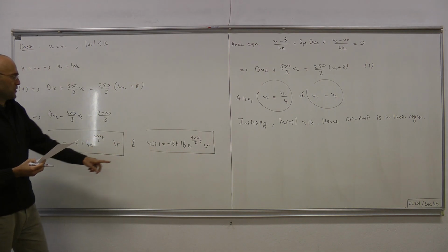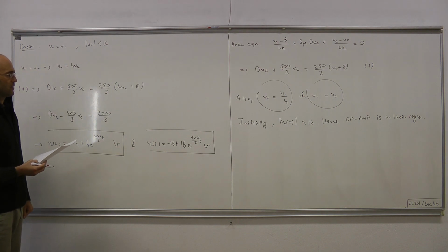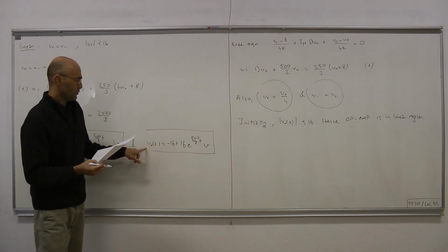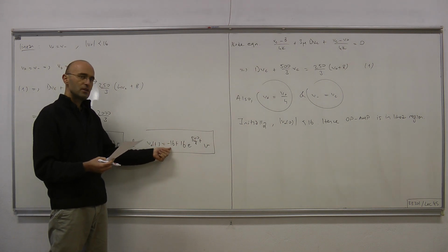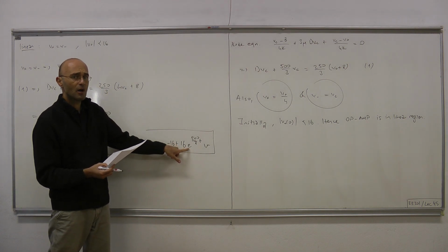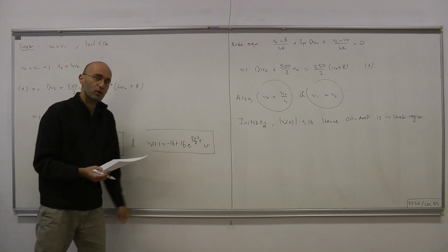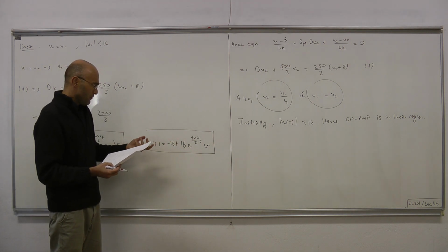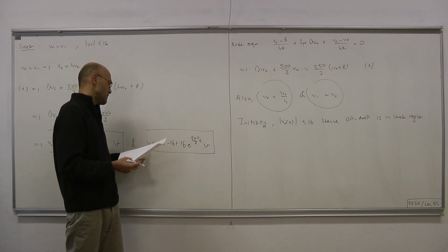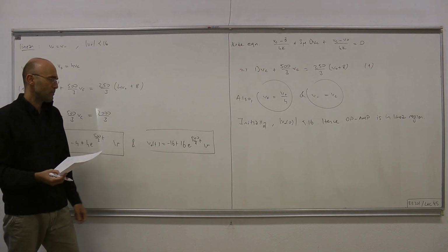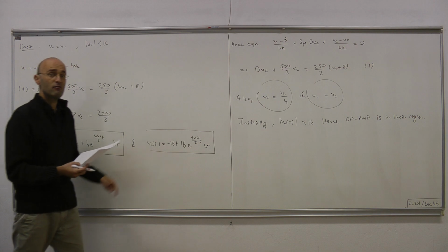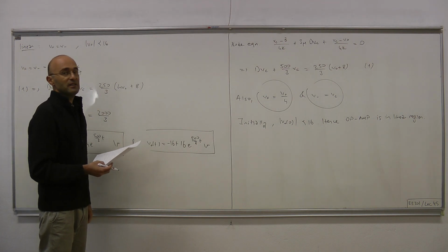Okay, now this clearly doesn't hold forever, because if you look at the output voltage, initially it's at 0. And what's happening is this term becomes larger and larger, and it grows exponentially fast. So V out(t) is tending to go to infinity, so that means very soon it will hit the border 16 volts, at which point it must leave the linear region.